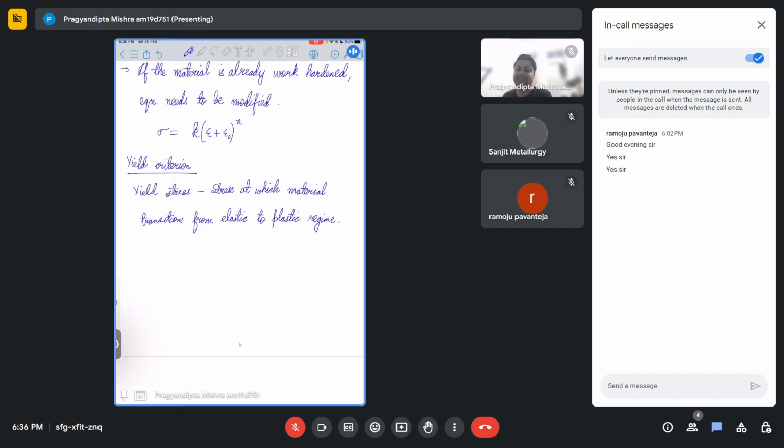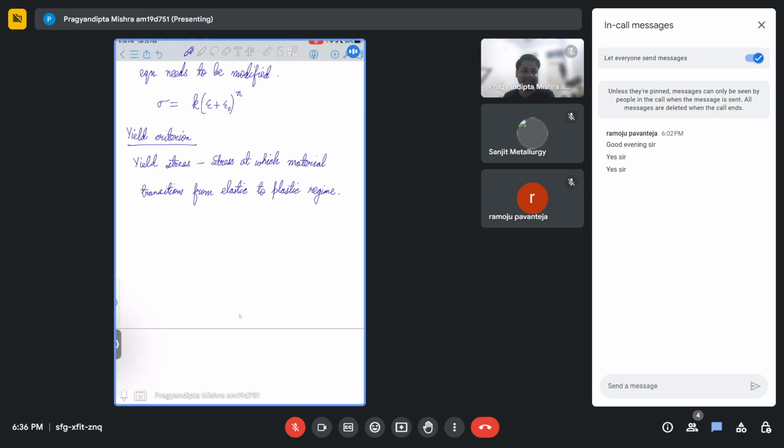Now, the second question comes: if it is so important to ensure that we do not reach the plastic region, we have to ensure that yielding does not happen, right? If we are looking at uniaxial stress conditions, it is very easy for us to talk about deformations, because you will have stresses acting along a particular direction, and you will say that if the stress does not exceed a particular value, which is known as yield stress, the material will not yield.